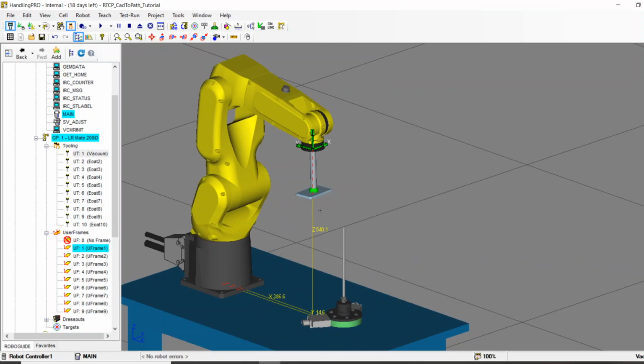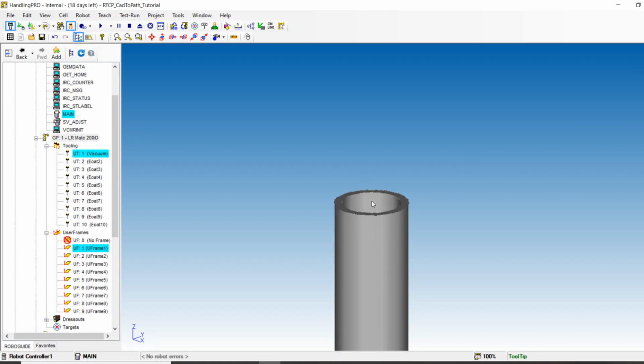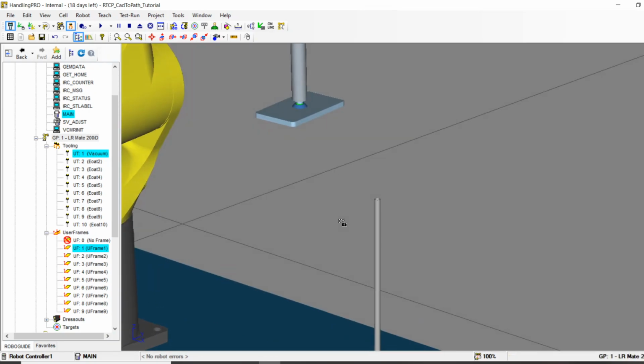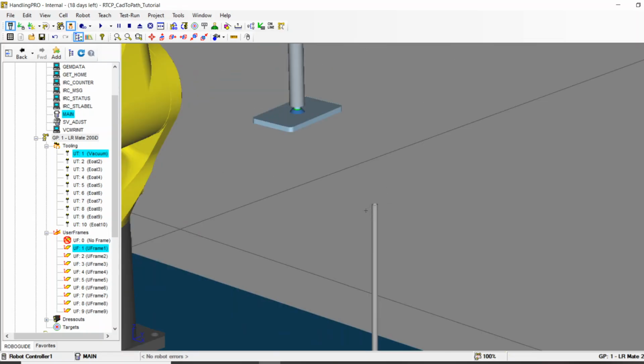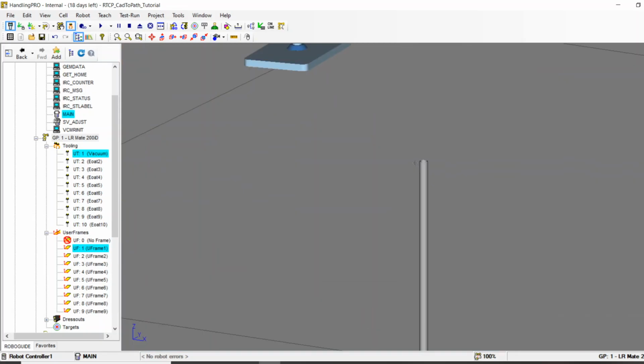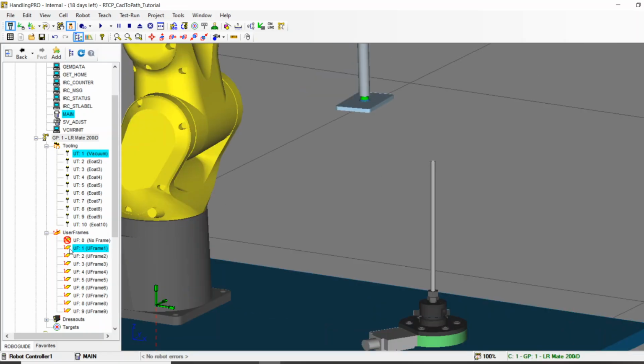All right, so here we go. The first important thing that we need to do is set up a remote tool center point, which is just a user frame out in space of where you want the part to touch. I guess for this example, I've got this opening that's an applicator, but maybe I'll pretend it's a deburr device, and I'm going to treat this corner edge as the point of interest. So here's what we'll do.